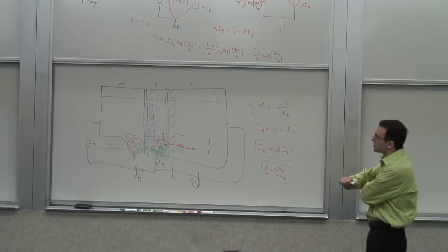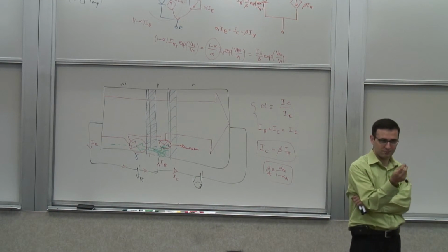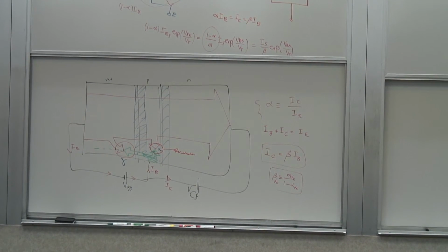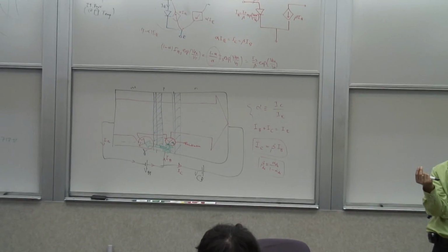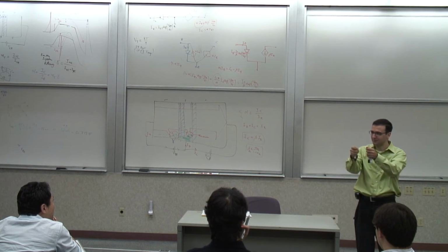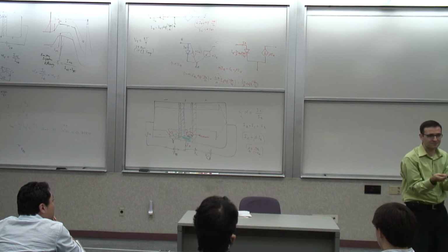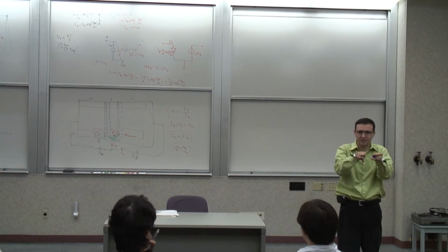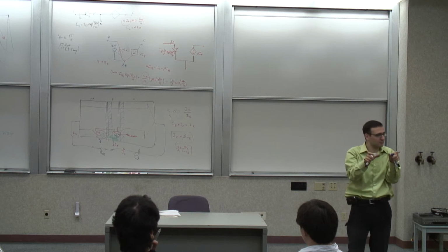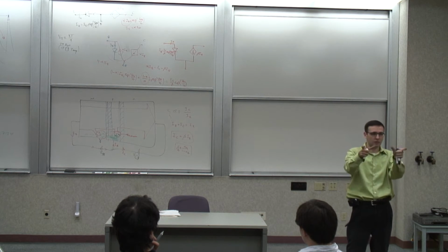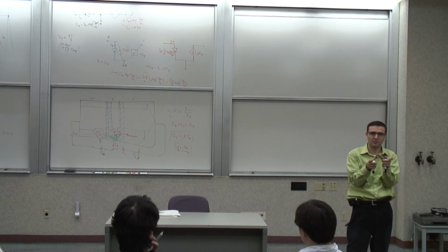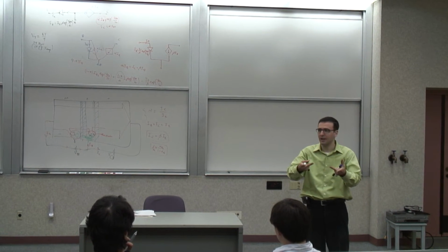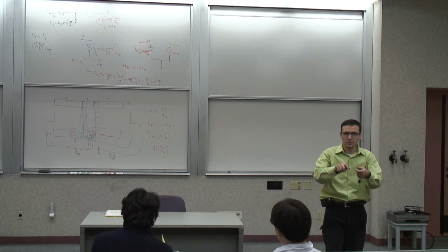And that's good. So let me ask you another question. I'm sure you've played with transistors at some point, right? Individual transistors. Do you know how to tell the three terminals apart? The base is relatively easy. If you have an ohmmeter, you identify those two diodes. You try different terminals, and you see that there's one terminal that has a small but measurable current in the forward direction to the other two terminals. By doing that, you can first determine which one is the base terminal, and also whether the transistor is NPN or PNP, depending on which way that current flows. Because if you reverse the polarity of your two terminals, then you will see no current flow.